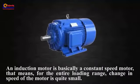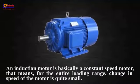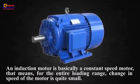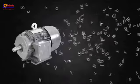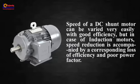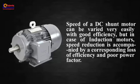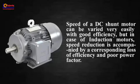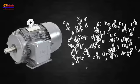An induction motor is basically a constant speed motor. That means for the entire loading range, change in speed of the motor is quite small. Speed of a DC shunt motor can be varied very easily with good efficiency. But in case of induction motors, speed reduction is accompanied by a corresponding loss of efficiency and poor power factor.